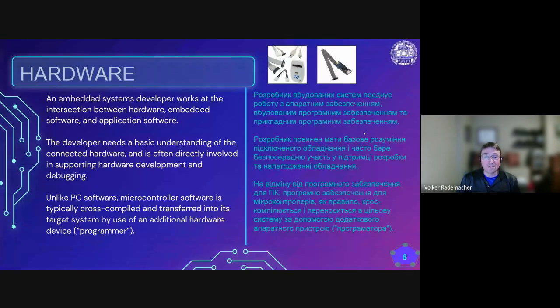You will also have to understand on the PC side that the Windows or Linux operating systems have limitations in terms of data requests. You might be offering data on a bus to the embedded PC, and the data might get requested or picked up in regular intervals most of the time. And then sometimes the PC just hangs, and the data will not get picked up. Your firmware will have to deal with not creating a buffer overflow, for example, if that happens, and either discard the data or indicate that a problem has happened.